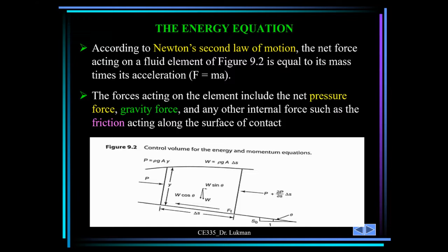Now, the forces acting on the element include the net pressure force. Pressure force is acting on the fluid element, which here is usually water. The pressure force, as we know, is also called hydrostatic force. The pressure force is synonymous with hydrostatic force, and it is compressive. Pressure force is always compressive and normal to the surface or to the cross section.